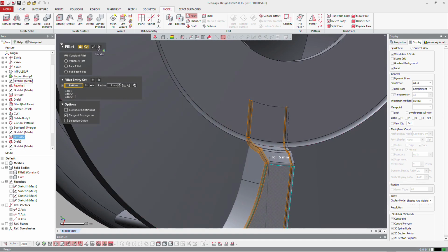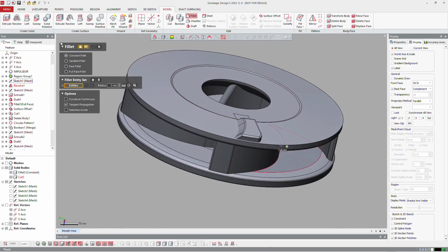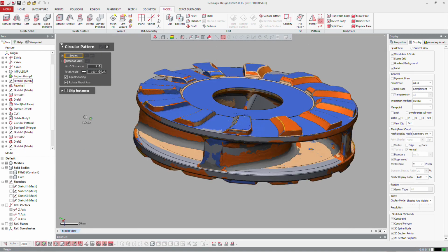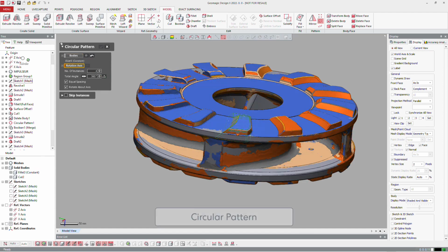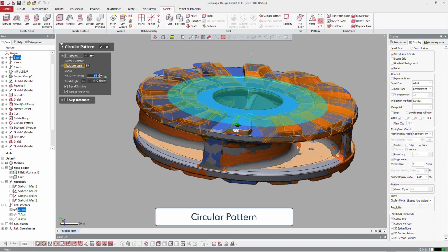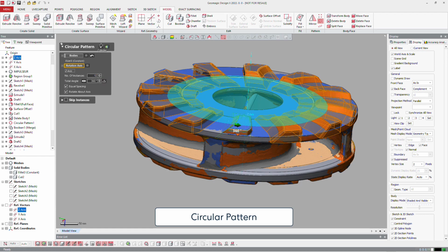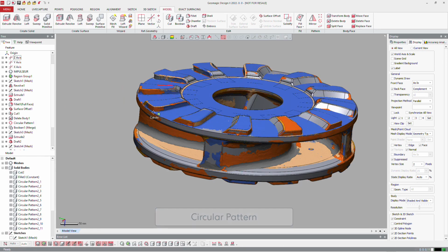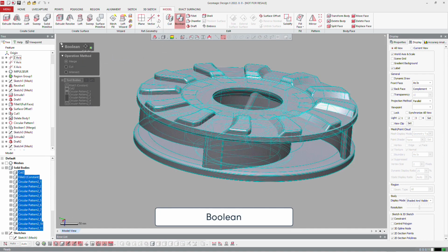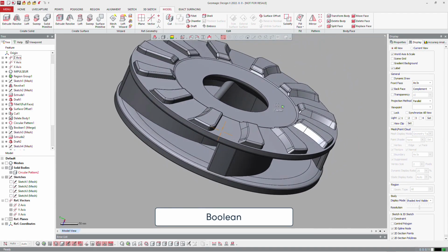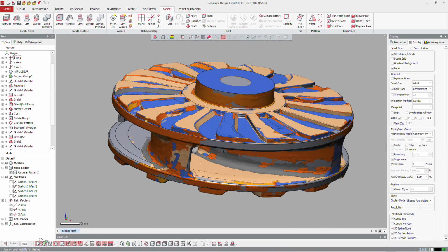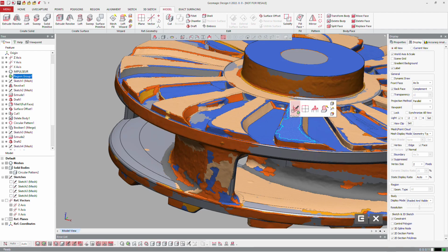And then you will be able to duplicate this body by doing a patterning. And you can use, of course, the cloud or the mesh to define the number of entities you need to do at the end. So here it's going to be this number, and adjust it just to be sure you have the right number. Of course, at the end, you'll see that you have some overlaps. When you are going to merge, the software simplifies everything in order to get the right shape at the end. So now you can make the same thing on the other side.